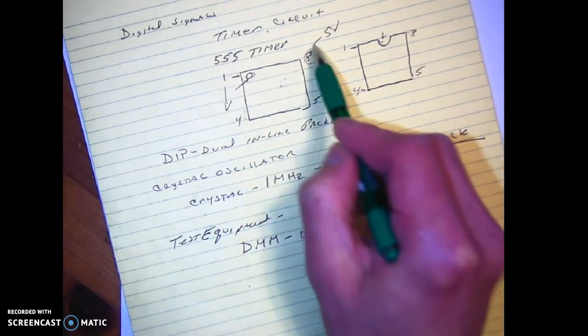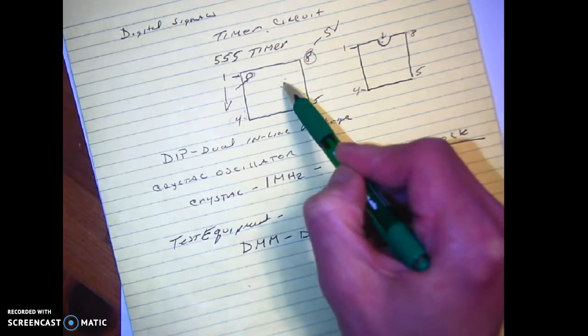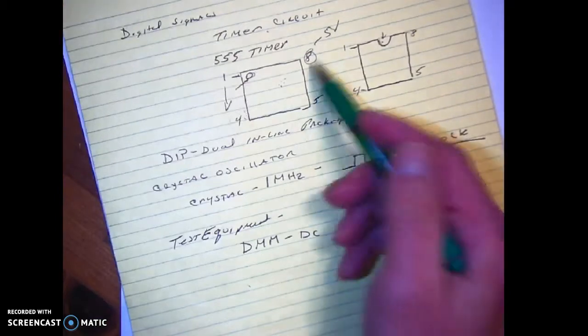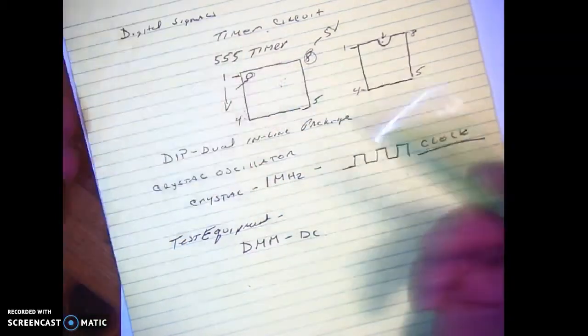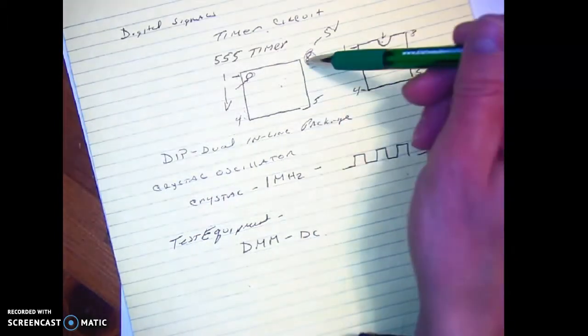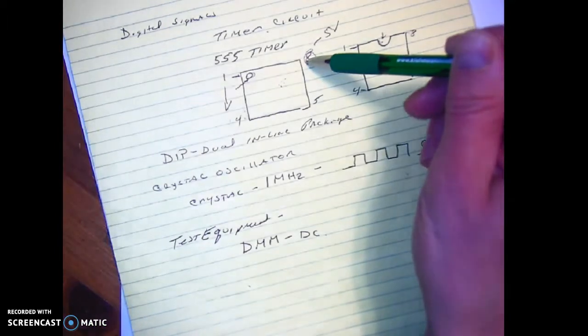This is reset. I'll talk about the reset in a second, but this pin 8, if I don't have 5 volts, the chip's not turning on. If I don't have a ground, I got nothing. I can't control the chip. Nothing's going to happen. It's going to be dead. So that's what the logic probe does. It's like my pen. I take it and move it there, and a little light goes on over here, and it says, "Oh, yeah, it's on. Good. Okay, we have that.